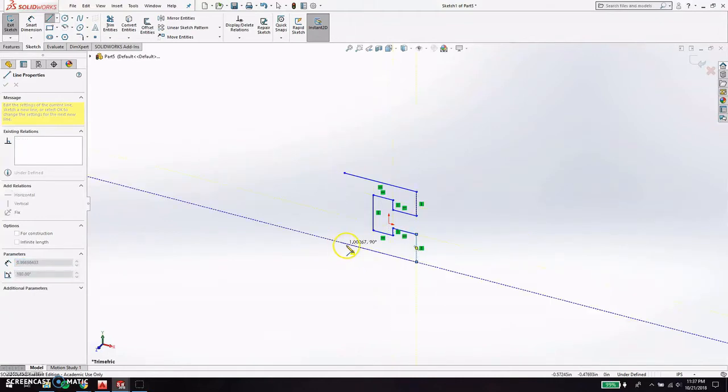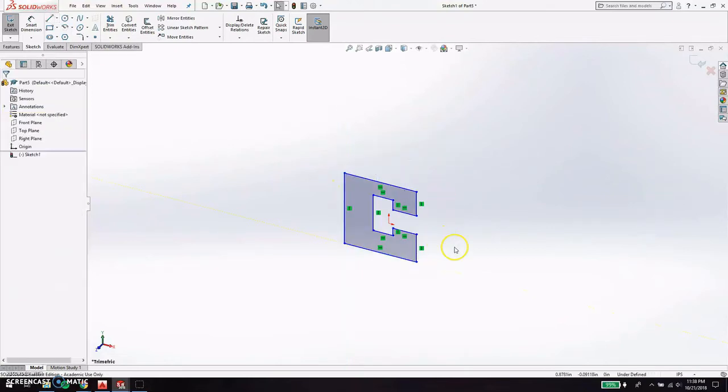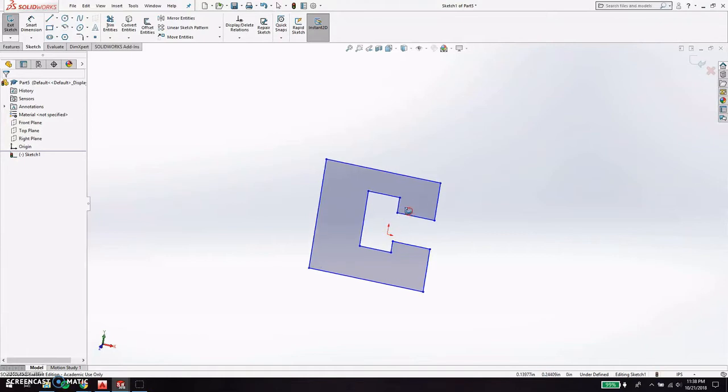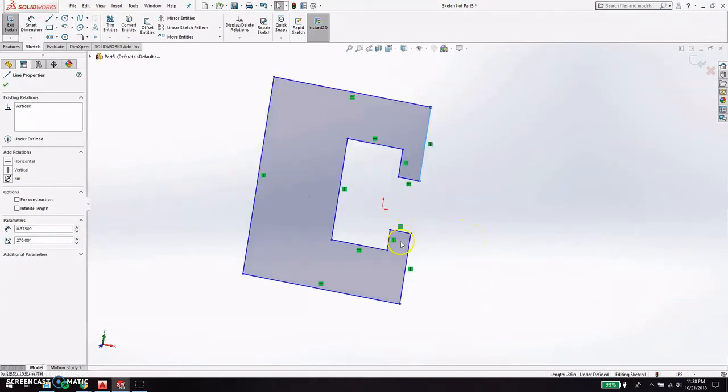So right now I'm making the female part first. Just make sure that you make things perpendicular. That way you don't have to worry about adjusting other things. We could go measure it in AutoCAD, but I'm honestly just going to make it up. So we know this has to match the exterior dimension of our big 1 by 1 piece, so this has to be 1. This is going to be 0.75, and you've got to make sure the other side matches as well. And then each of these is going to be 0.375. Just putting some numbers together here, making sure everything's perpendicular.